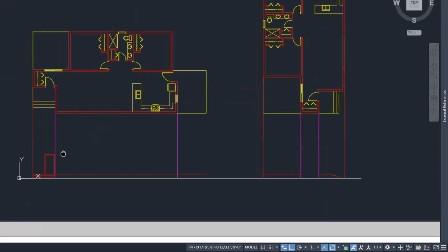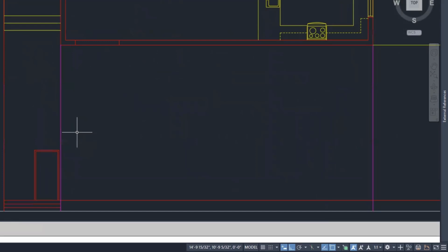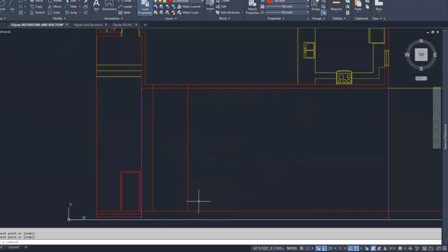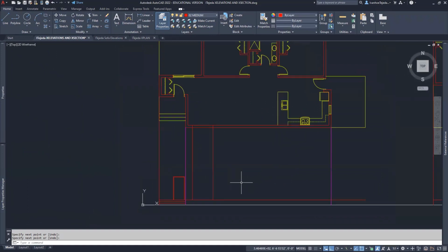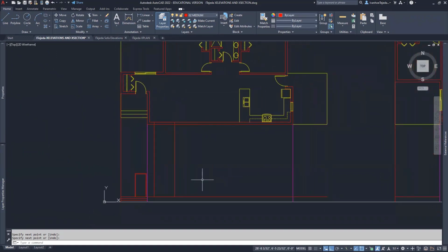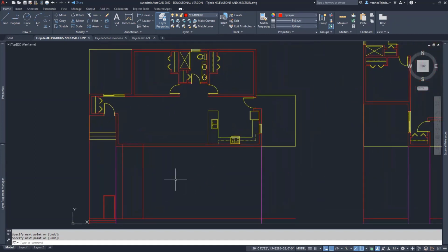So now that I have that in here, I can go ahead and draw my lines. So I'll type L, enter. And let's say I would like to have my window here, right? I'll take it all the way down to that level, enter. And then I can draw the line again from here down like that. And I can look at it and ask myself, is this really what I want? Because if it's not, I can go ahead and make the changes. Or let's say you want to put off putting the windows in, you just want to get the elevation started. You know that at any point you can go back, you can make changes, make some revisions, and you're all set. I'll give you another example.